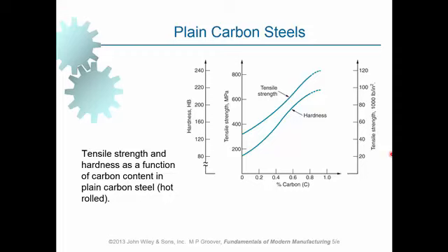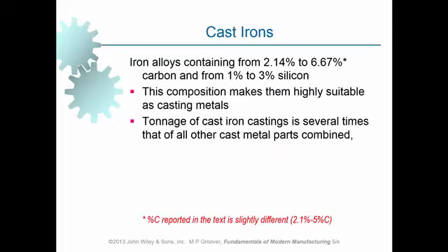As I said before, a trade-off is often required between the different types of properties that can be found in different types of steels. And cast irons, as I said, the carbon content of cast irons is within this range, within 2.14, that's the maximum solubility of austenite to carbon, all the way up to 6.7, or to be more accurate, 6.67% of carbon. Beyond this, at this point, we will have 100% cementite, Fe3C.